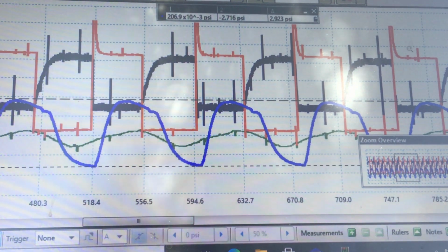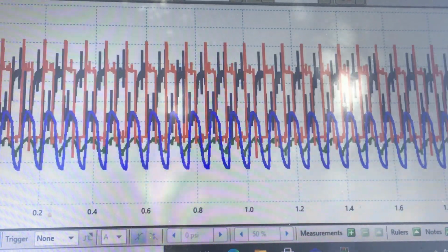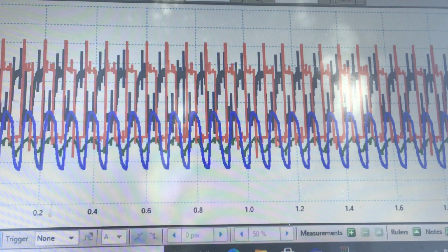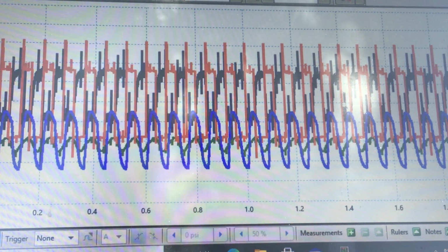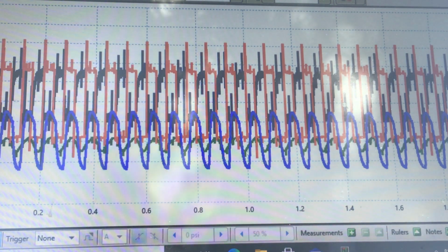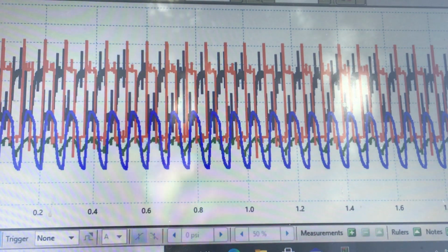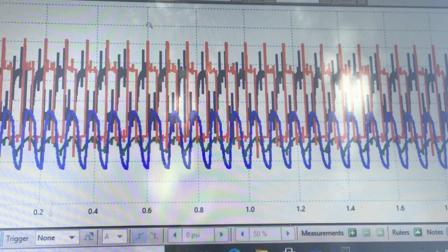This is a very tightly monitored system, so they're not going to get the full 20 inches. This is basically pulling some unburned fuel into the engine to be reburned, so it doesn't get into the atmosphere. This, of course, is an emission control system. And bear in mind, sometimes canisters are empty in there. You're going to get more air than fuel. So it's dependent on how saturated or unsaturated the canister is.